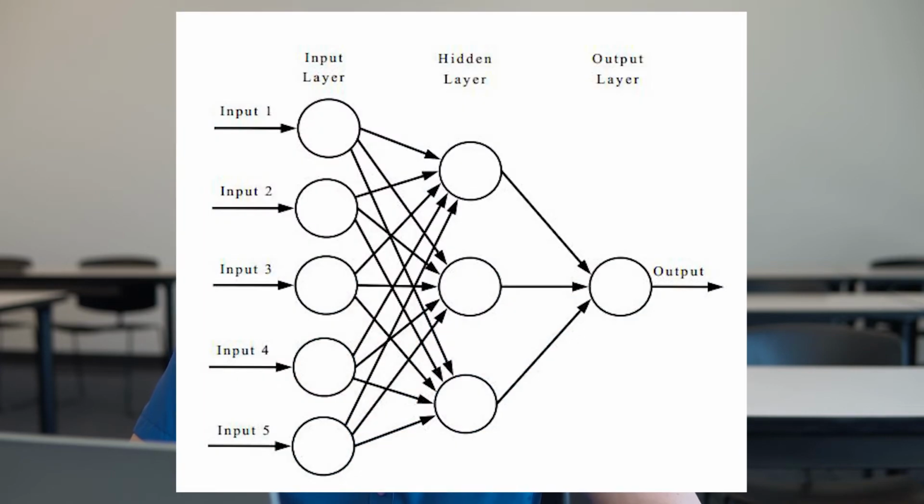So once the completed model was trained, we were given a weights file. We used darknet to train our model. After that, we had to convert the model to a different format. We chose Caffe. Darknet is not supported on Xilinx products. So we convert it to Caffe, and then we have to quantize the model.